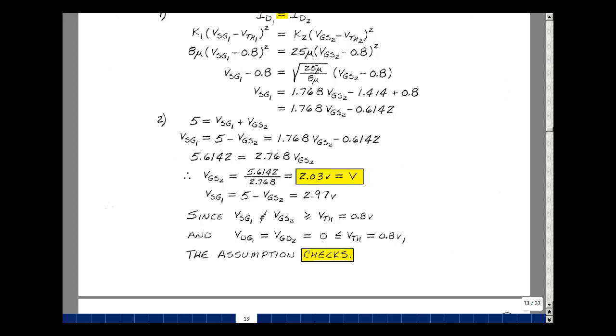This circuit is also called a voltage divider, and we'll see later in IC design courses that resistors take up a lot of space on an integrated circuit chip. We try not to use resistors. In this case, we're going to use two transistors, and by playing with their areas, in other words, their gate width and length, we're able to pick any voltage we want divided down from the power supply. This is a great building block in ICs. And this is supplemental problem 4.7.